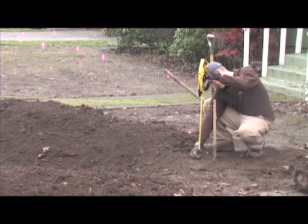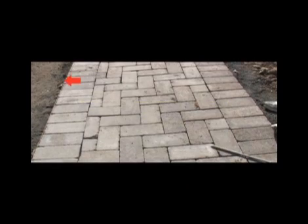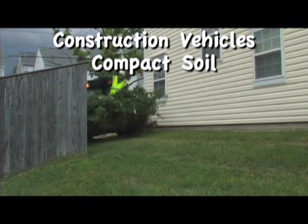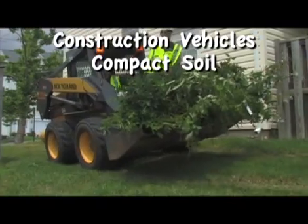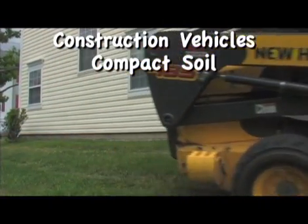As with conventional paving, lay out the surface dimensions of the structure using string and framing to ensure the project is both level and contained. Compacting soil reduces its ability to allow water to infiltrate and defeats the purpose of installing permeable pavers. Therefore, excavation must be performed without using heavy equipment on the site where the paver system will be installed.